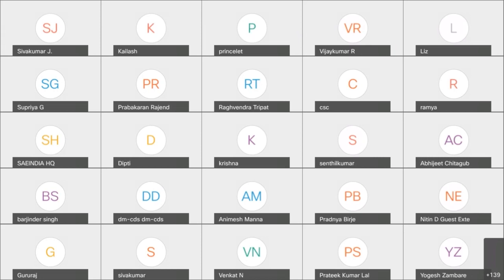And the third one is the communication related aspect. The problems with communication are data loss, delay in data, or corrupted data and so on. To avoid these, you will have end-to-end protection with a CRC check, timeout monitoring, and sequence monitoring. Also there are source verification techniques and so on. If you bring in such safety mechanisms, that will ensure against communication related failures. So these are the various techniques and methods suggested for freedom from interference.